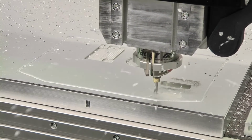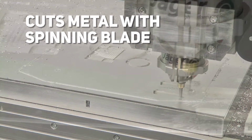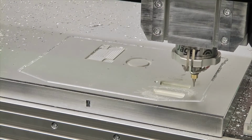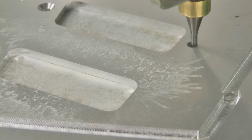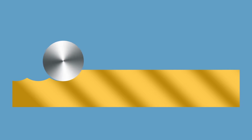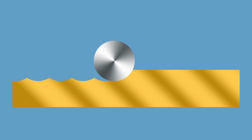Milling is a process that removes material by performing many separate small cuts with the use of milling cutters, which have numerous cutting edges, called flutes or teeth. A milling cutter spins at very high speeds, repeatedly cutting into and exiting from the material. The blades of the cutter take swarfs of material at regular intervals, creating a distinctive characteristic in the finish.